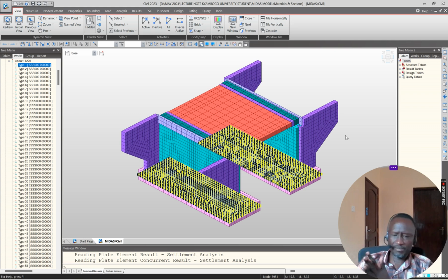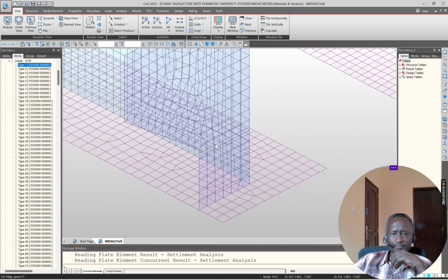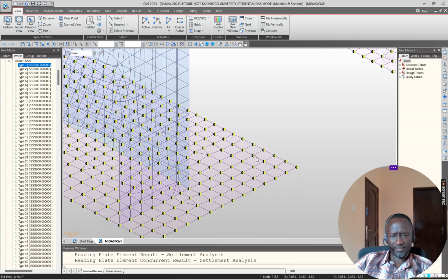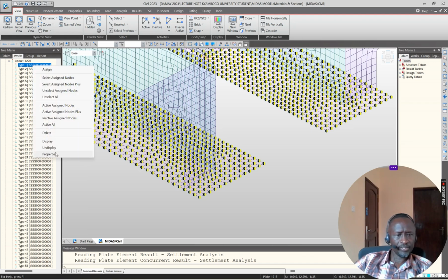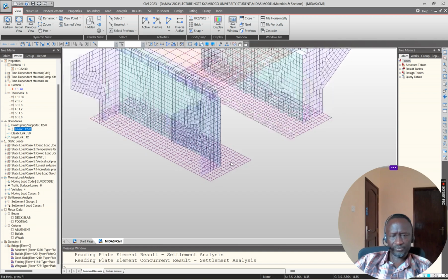But if you go to the manual and your literature, you should be able to get the right thing. So you have to know the subgrade reaction of this foundation. Once you get the soil pressure and you know the allowable deflection, you calculate, and input that into the software.